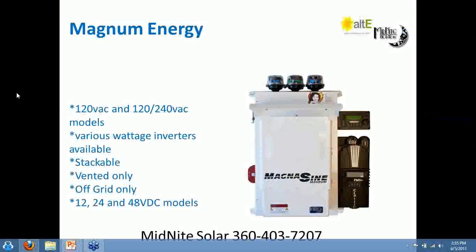So you can't just simply backfeed that panel because, well, A, you can't really power the whole house because you've probably got a lot of electric loads that are too big for the inverter. And B, it would backfeed the grid, which could potentially kill somebody and maybe blow up your system. So you need a critical loads panel, and typically it'll get installed right beside the main panel, and the electrician will pull the critical loads out of the main panel and bring them over to the critical loads panel. And then the inverter goes in the middle between the two.